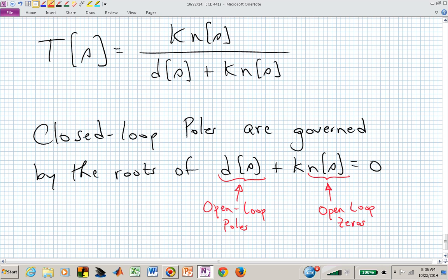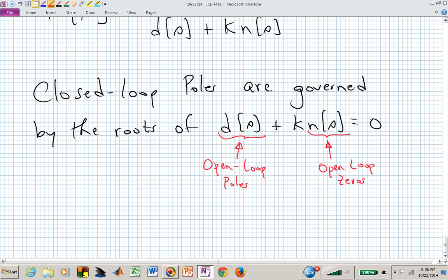And what we want to know now is how do those closed loop poles behave as a function of this adjustable gain K. I always am doing this. I apologize for those of you that are home. You'll just have to come to class sometime and see my movement of this knob. K is a knob. It's an adjustable variable. We want to take that knob and move it from 0 up to infinity. And we want to ask, how do the closed loop poles behave as K moves from 0 to infinity? And that's our root locus.